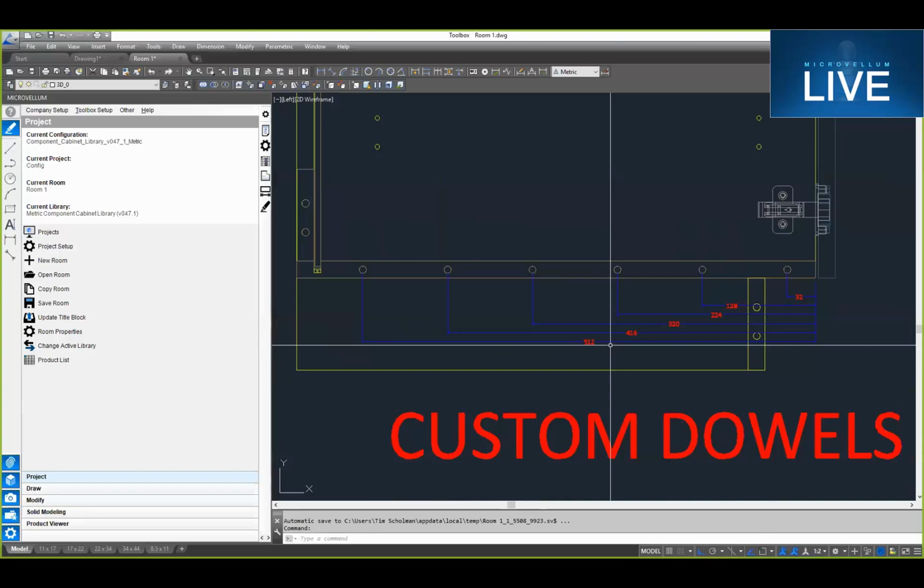So again, usually used either with a fixed head or a CNC head horizontal boring machine. If you're using a CNC horizontal boring machine, you don't want to use barcodes for each part. That's certainly something that you can do with a CNC machine with Microvellum. You can just have labels printed with 2D horizontal barcodes for the horizontal boring, and you can scan those parts and run those programs directly.